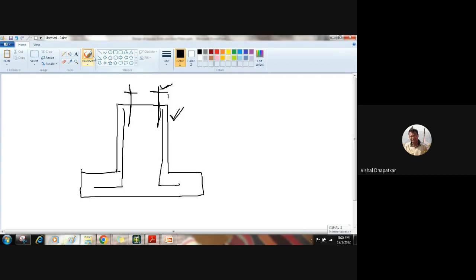So how will the bolt elongate? Initially the bolt will be like this, right? Once the force comes, the bolt will try to elongate. Its area will get reduced at some location. As the force goes on increasing, its area reduces further, and ultimately, after reaching its yield strength, the bolt will break.